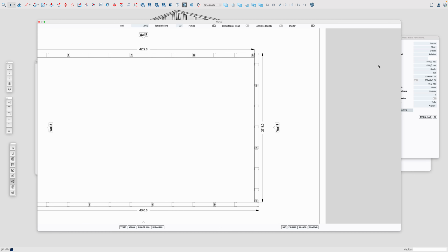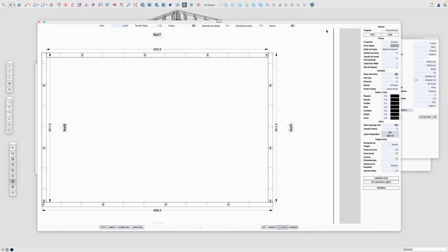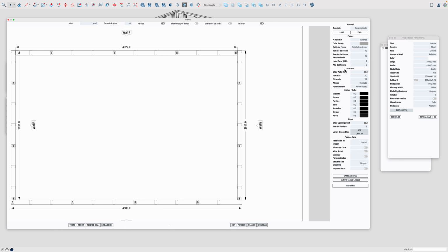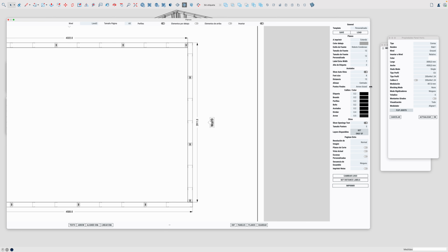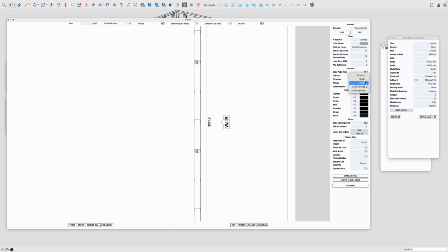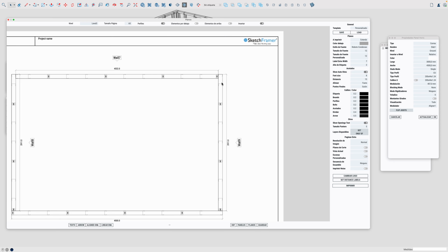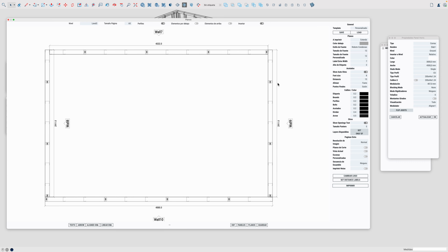So what you can do is bring up these options, and you can show or hide these auto dimensions, change the size of the fonts, and the distance from the objects, let's say 15, and you see that I can massively edit the distance, and also if I want the dimension centered or outside, and the kind of tick that we can use.